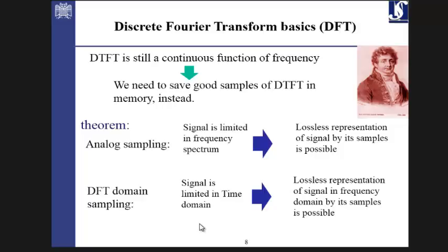So we talked about the duality of the frequency and time domain, the ideas. We said that because the DTFT is continuous with frequency, still we're not able to take the DTFT as something inside the computer and to do the process. So we need to have a surrogate, a replacement, such a way that it's representative enough and it still has the information of the signal in the frequency domain, and you can also cope with it inside the computer. You can do the process using computer programming.